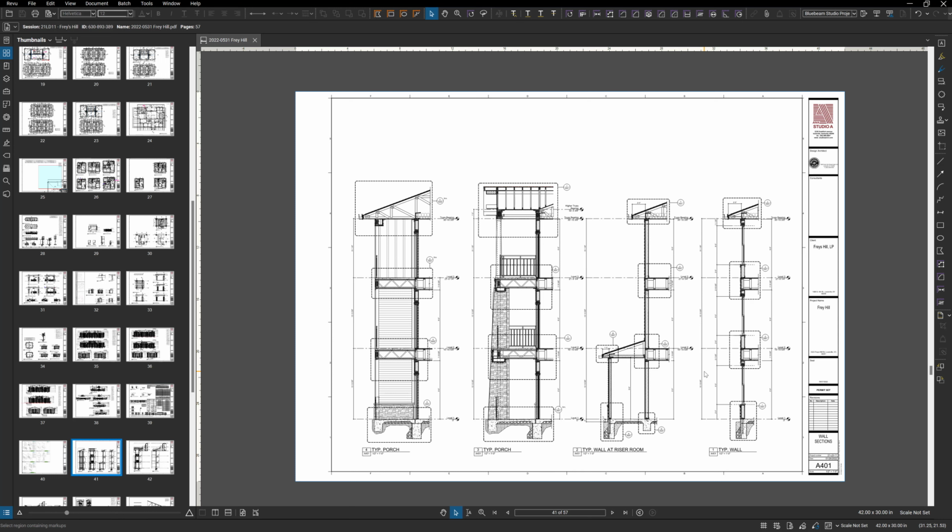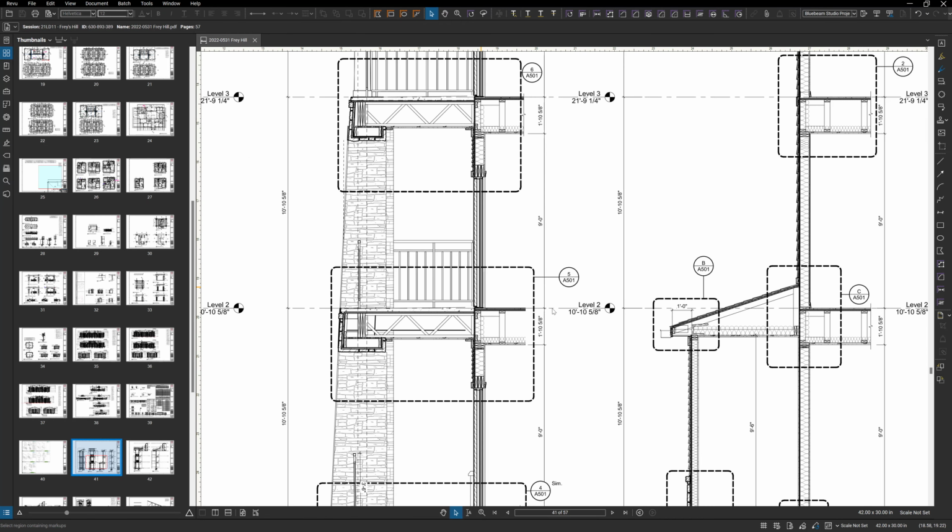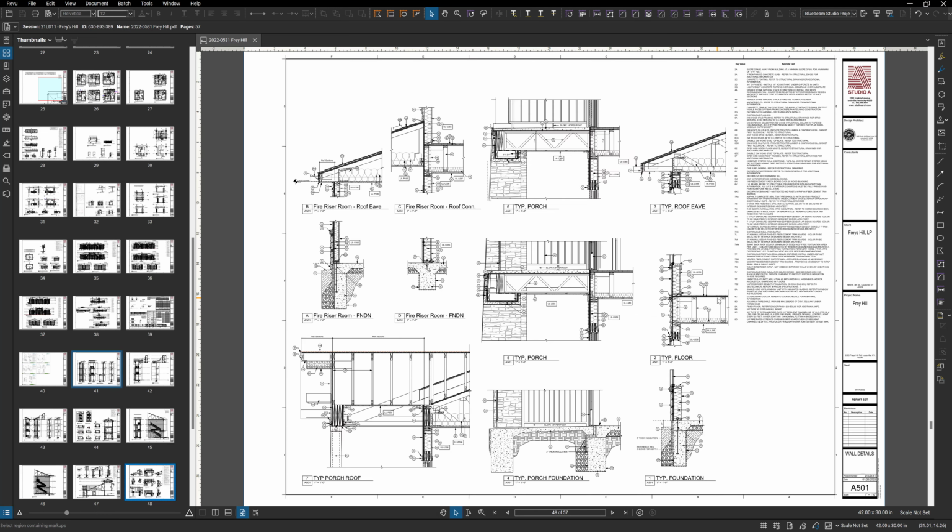Okay, wall sections. These are fun. The intent here is that I try to get people in the habit of making wall sections show the basic assembly graphically, and showing a lot of dimensions for verticality. You do your X and Y plane on the floor plans for dimensions, and then your sections cover your Z axis for dimensions, and then they just cover callouts, right? So how to build everything should be in the 500 series sheets, right?